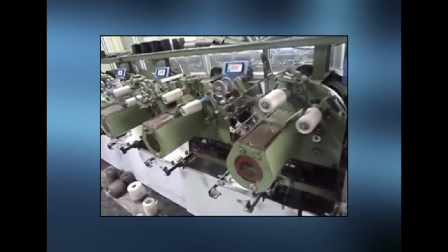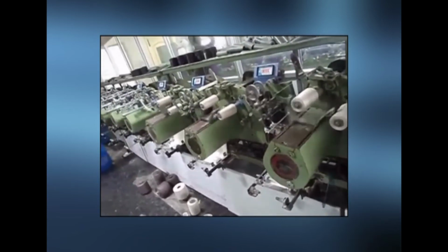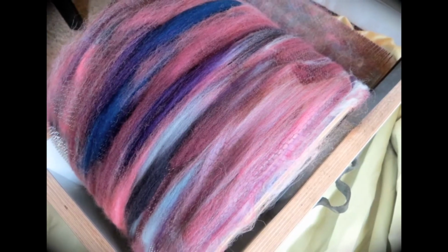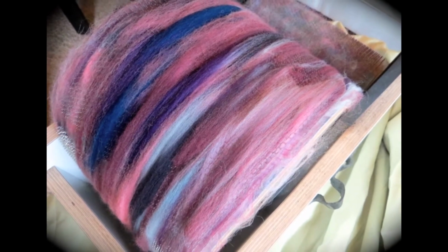So, many fibers which are available in the market today are either man-made or synthetic, except those which are available in fiber form, especially the natural cellulosic or protein fibers like silk and wool. But these nylons, polyesters, polypropylene and all other fibers are not available in fiber form. And so, the chemical spinning is applicable to these fibers, because the manufacture of the fiber is also involved in it. All these fibers are mostly filamentous in nature, because they are manufactured as filaments. Unless it is blended with some other fibers, they are all produced in a filament form only.